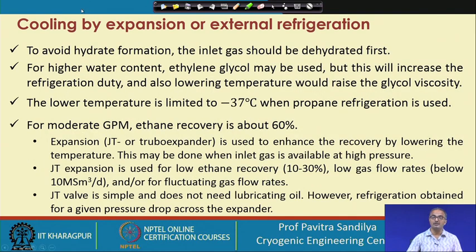And there may be a possibility of hydrate formation, because if there is a substantial amount of water in the inlet gas, then this water may form hydrate, and it may form hydrate with the hydrocarbons themselves, like methane forms hydrate, ethane forms hydrate. So all these gases may form hydrate with water, and so to reduce the chances of the hydrate formation,